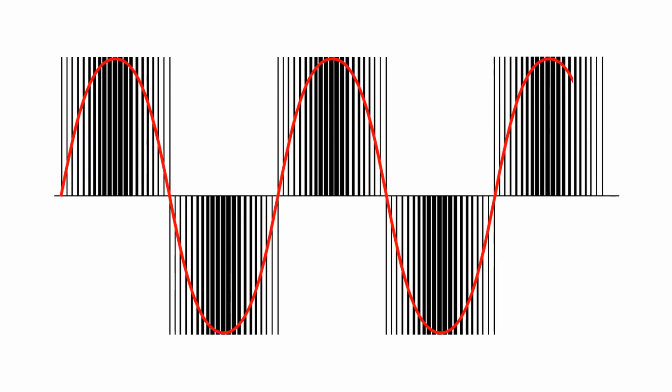The DC is turned on and off, pow, pow, pow, pow. Then it flips back. Then it flips again. What is this starting to look like? Yeah, a really lousy looking sine wave. Well, with the spacing of the bursts of the DC, the usable power in there averages out to look something like this to the motor.